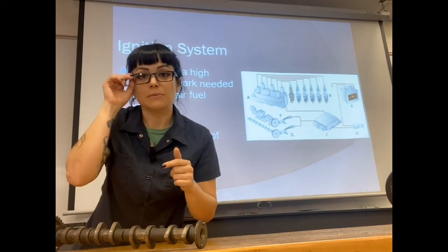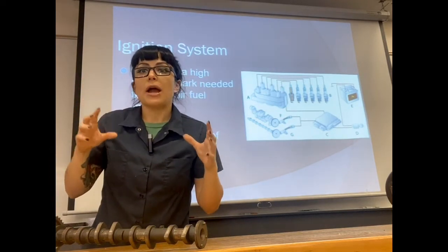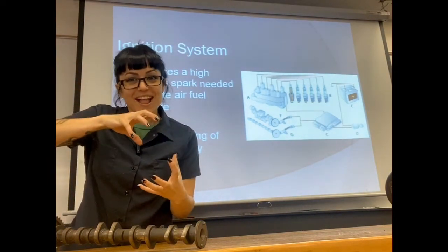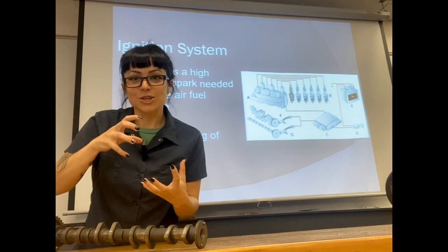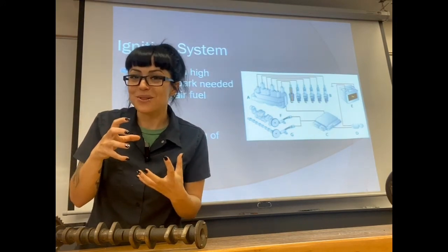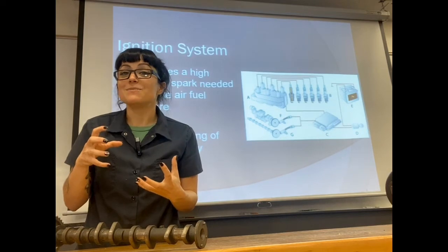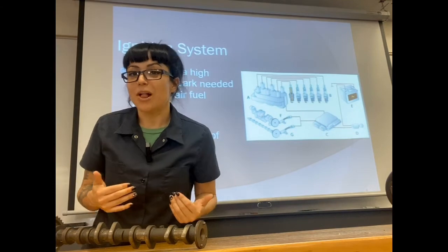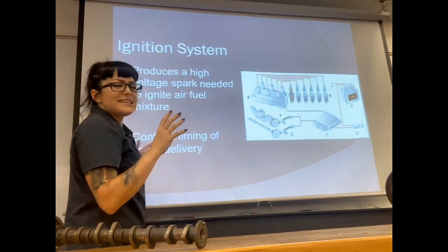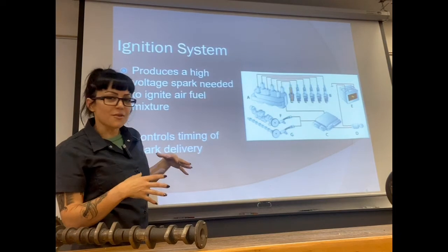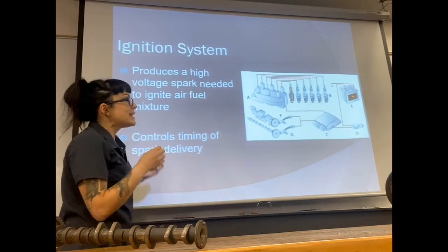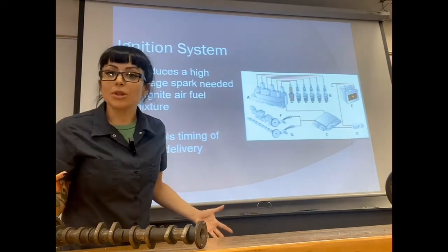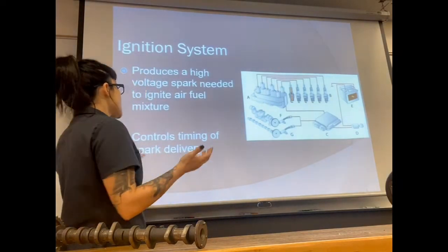We'll get into that later, but when we are trying to ignite the air-fuel mixture, we are squeezing air and fuel, and then what? We need to blow it up. Well, the only way we can blow up an ignited air-fuel mixture is by some sort of igniter. In this case, it's going to be a spark plug, and in a diesel, it's a little bit different, but in this class, we're going to talk mainly about gasoline engines. And in gasoline engines, we need a spark plug to ignite that air-fuel mixture. When we ignite it, it explodes, and it does everything that we need it to.